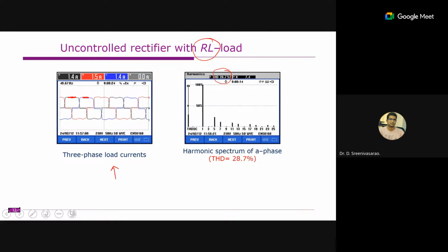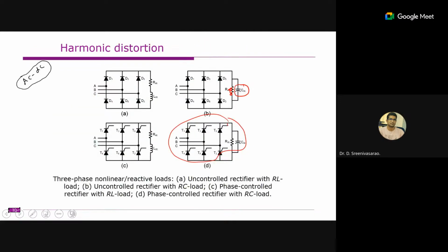The difference is that conventional rectifiers are based on diodes or thyristors, whereas active rectifiers or active front-end converters, which do the job of AC to DC conversion, are based on MOSFETs or IGBTs. MOSFETs or IGBTs are self-commutated devices, and there are certain advantages with them.